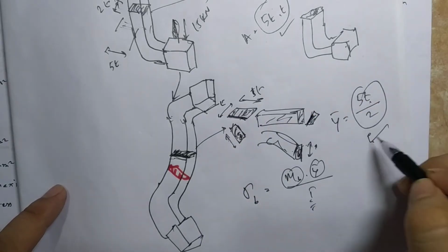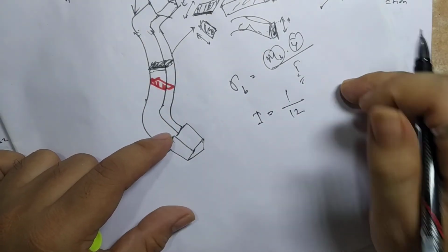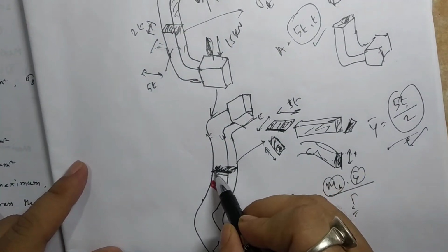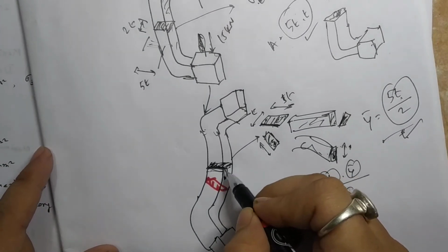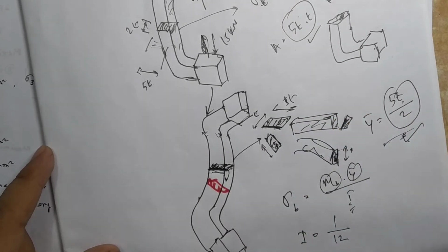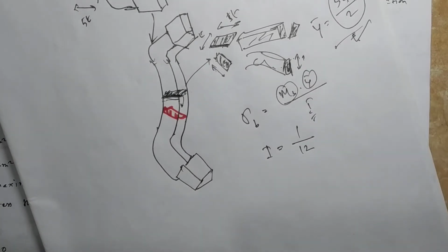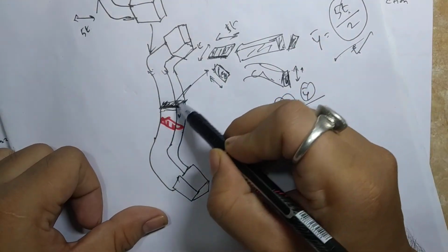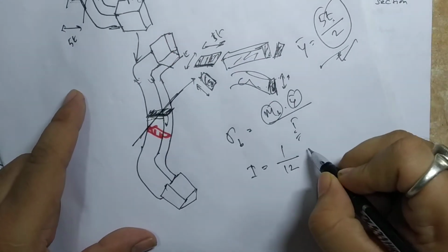Okay, so half of 5t, that is 5t by 2, is y bar. And yes, just try to find out this 1/12 whether it will be 5t into t cube or t into 5t cube. Yes, quickly think about it. Look at this: this is the dimension that has tilted. The dimension which is tilted, or oriented, will have the cubic index upon it, and the dimension which is parallel to the axis about which the rotation has taken place will not have the cube upon it.